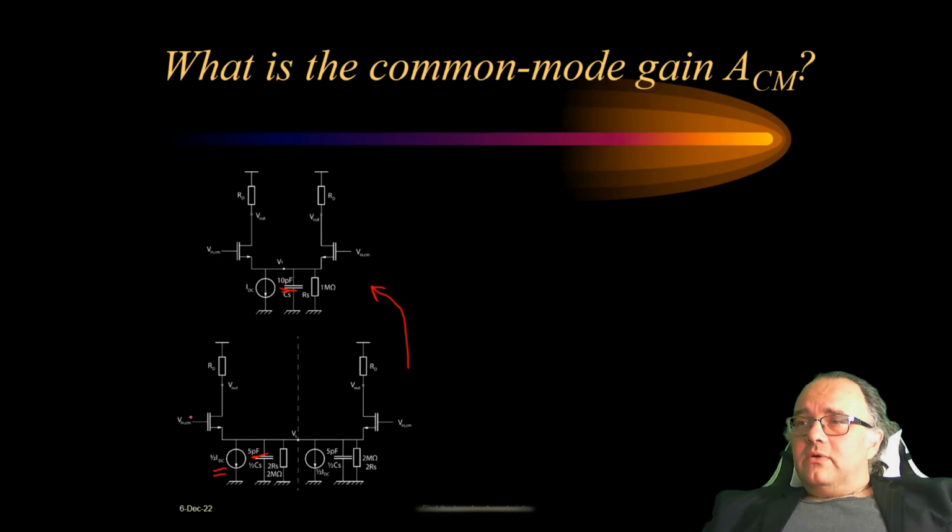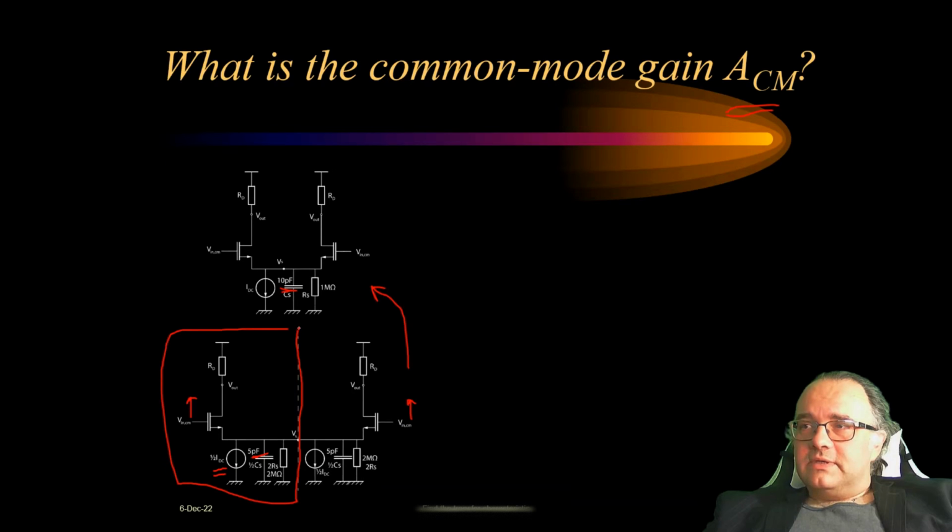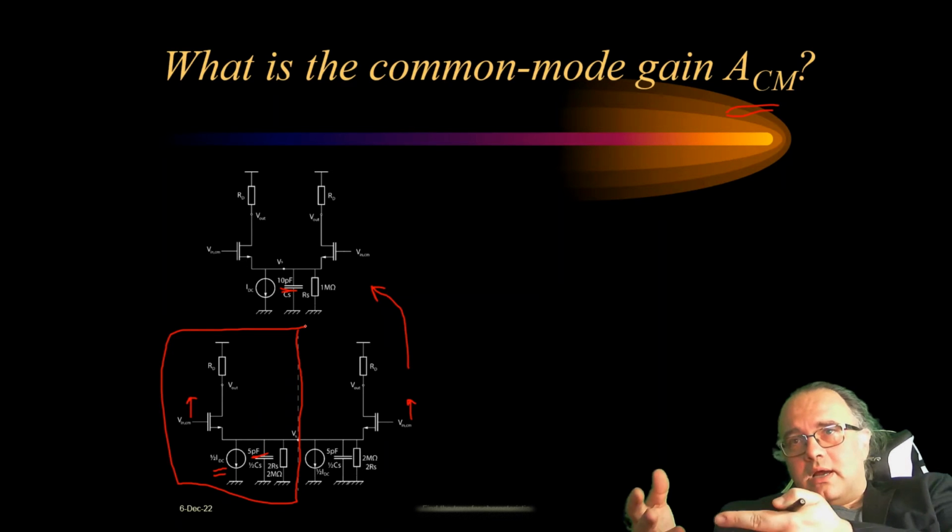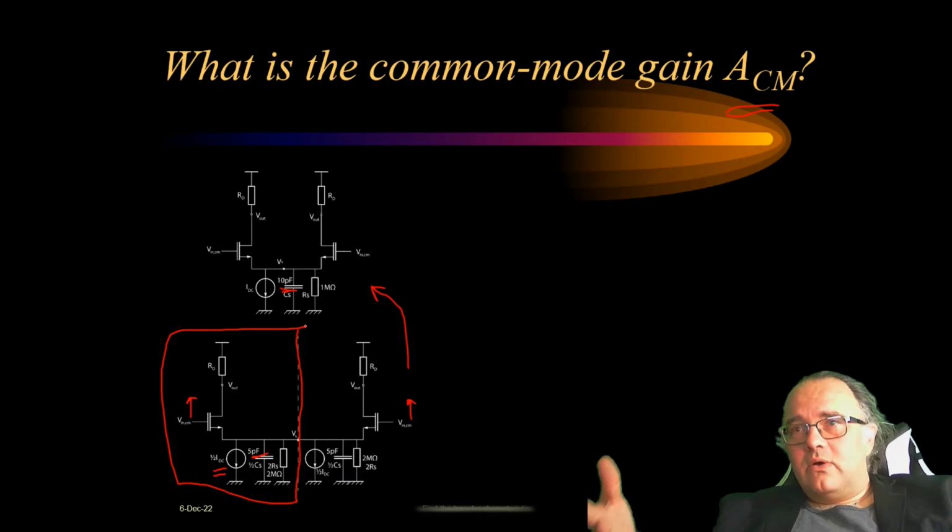And because the input signals that we analyze are common mode, meaning they change in the same way, analyzing only half of the circuit is absolutely enough, because the other half behaves exactly the same way.